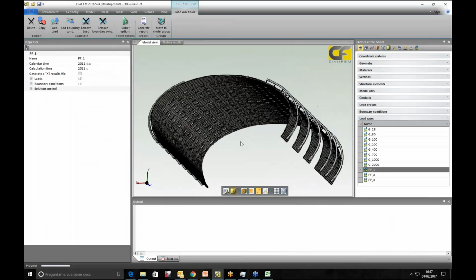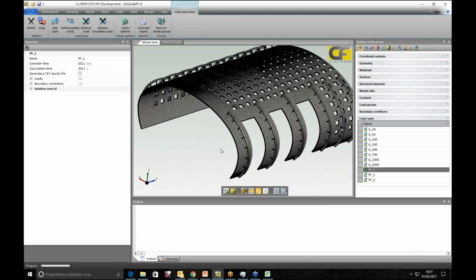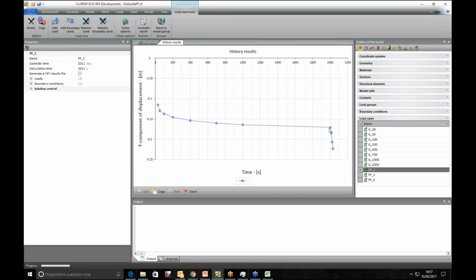So we can say now that due to these thermal loads, the connection between the steel stiffeners and this concrete layer fails, maybe with concrete cracking and crushing around it, and when that connection starts failing, also due to large deflections, we start having an unequilibrium step and collapse of the structure.